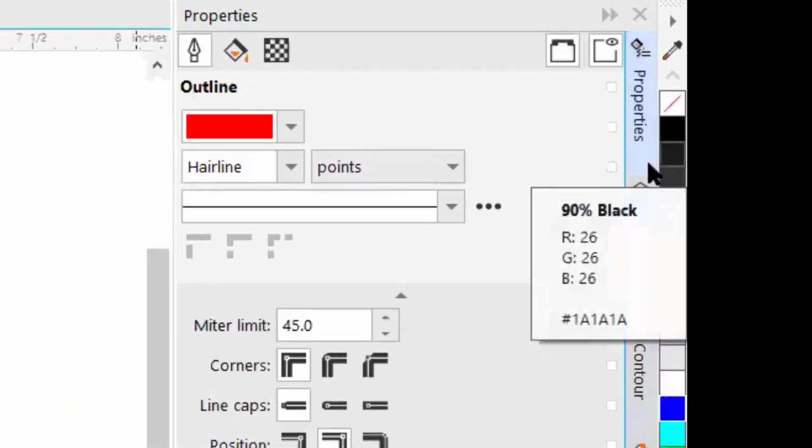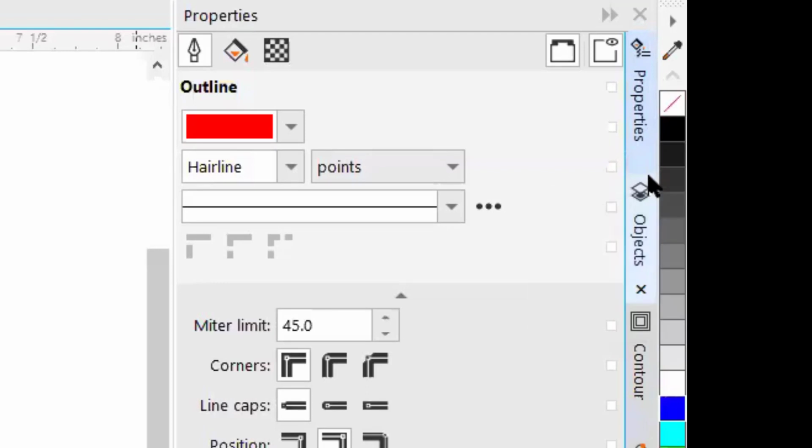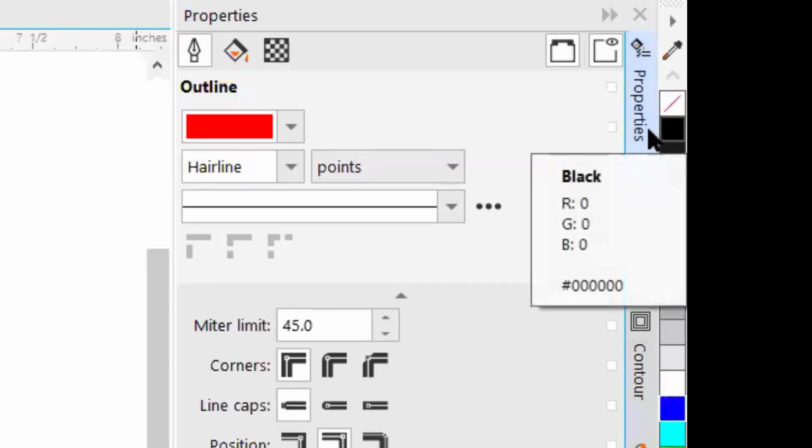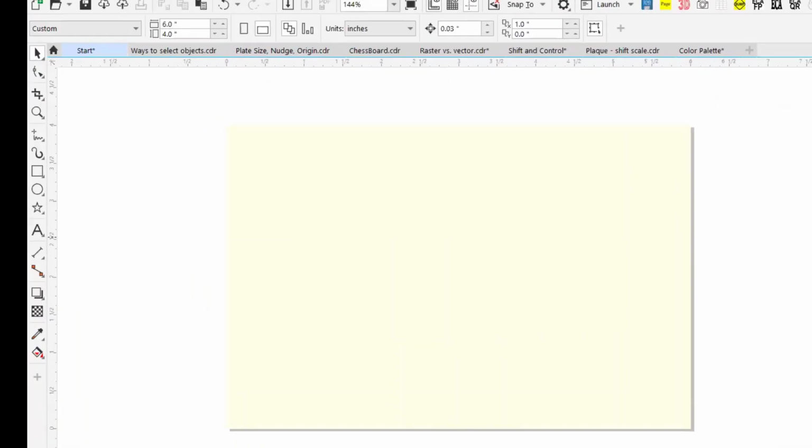All the way to the right, we have our color palette. Now you'll notice that we're using RGB color palette, which is the preferred color palette for Epilog systems. It doesn't mean that we can't run CMYK, but RGB is the preferred, and it's going to give you the expected results when you laser black and when you laser white in your objects.